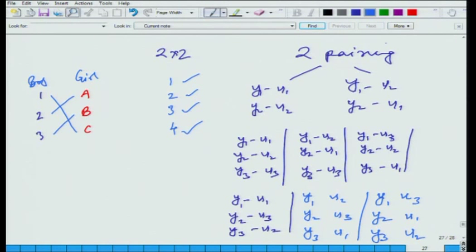Which one to implement? That is the question. Should I implement this? Which one gives me favorable multivariable interaction where the off diagonal terms are not as severe? If the multivariable interaction is not as severe, the need for detuning will not be as severe and I will get better control, right. It is like matching compatibility in couples.